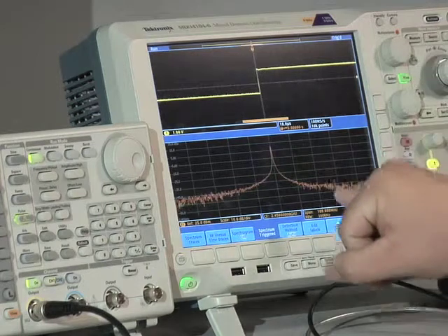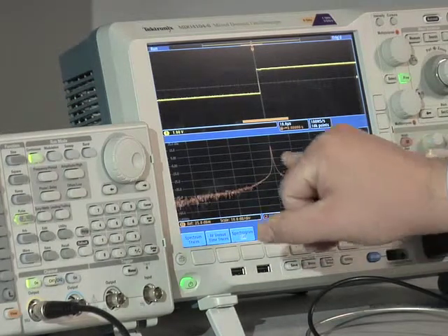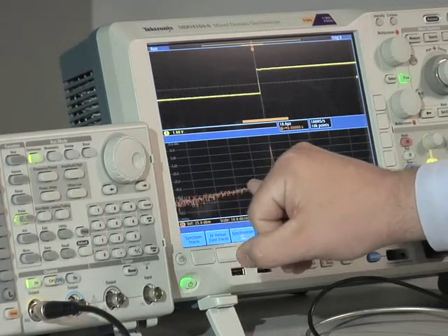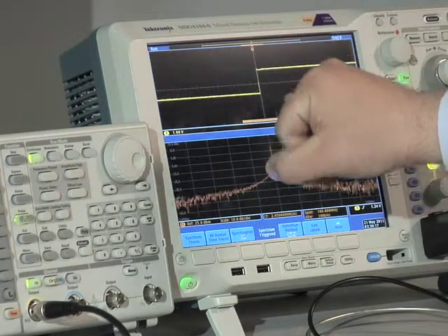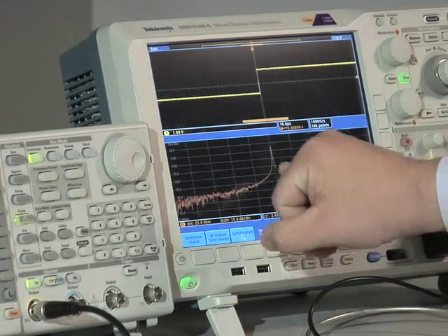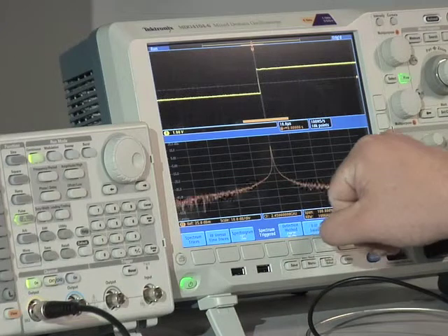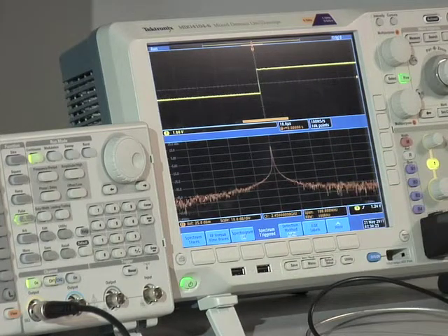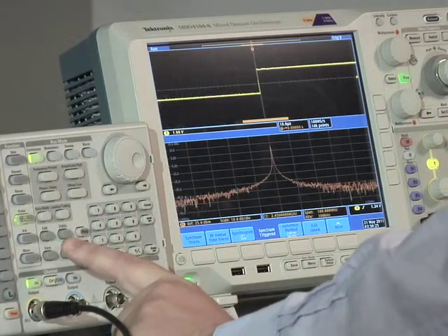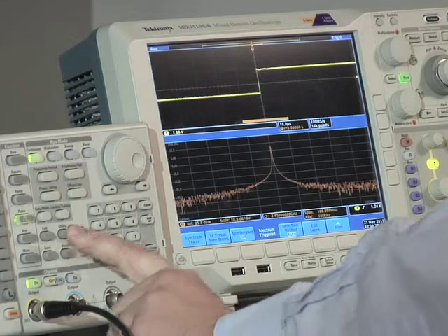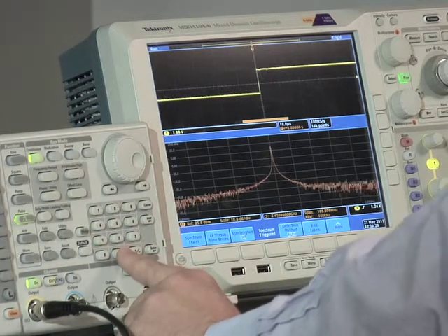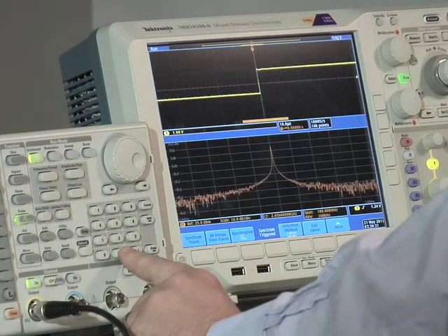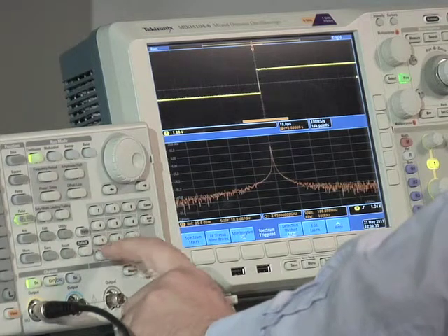And so now we're looking at the spectral purity of the power amplifier. So you can see the impact of the rising edge of that pulse and the consequences of that, we have some spectral splatter. So what I can do is change the rise time of that, and we will change it from, at present, 50 nanoseconds. We'll change it to 100 nanoseconds.